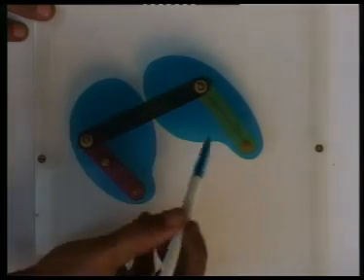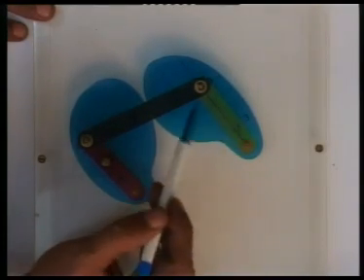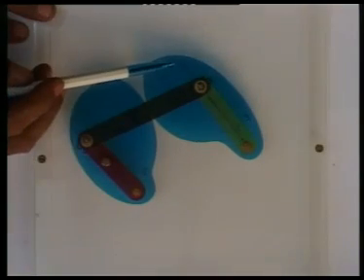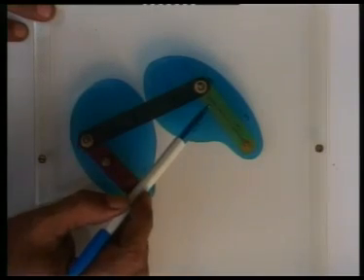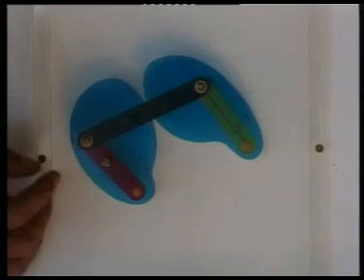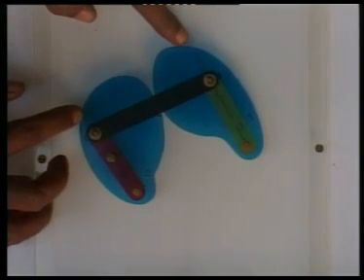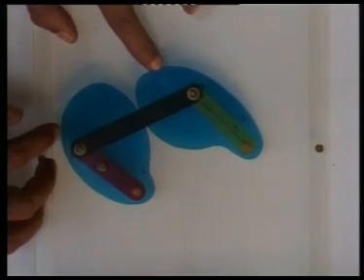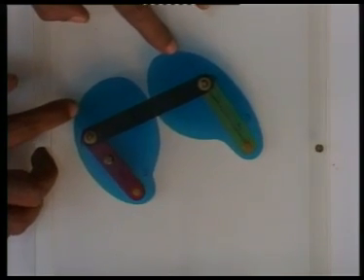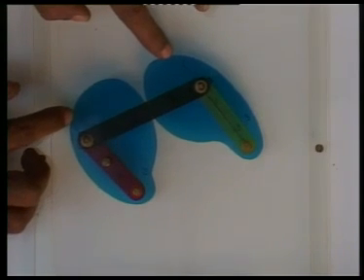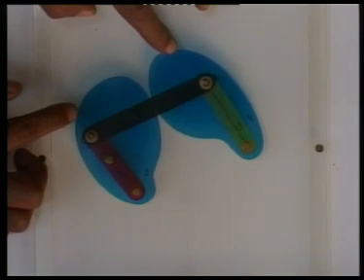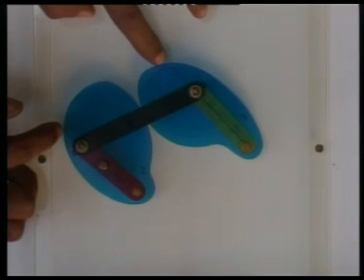To distinguish the movement of body 3 in the lower pair linkage and body 3 in the higher pair mechanism, let us notice these two lines: there is a red line on this body and there is a blue line on this body. Now, around this point, as we see, these two lines move almost the same way, because the velocity and acceleration relationship between the original higher pair mechanism and the equivalent lower pair linkage is just the same.